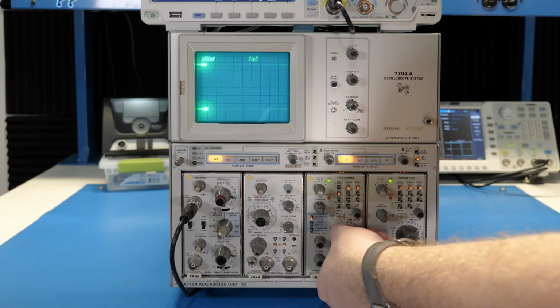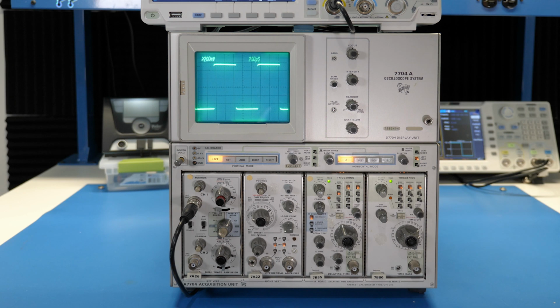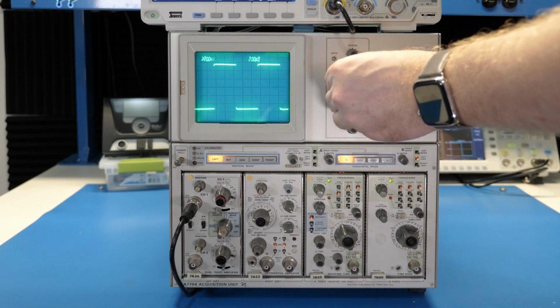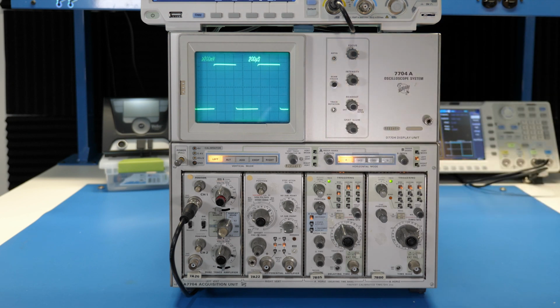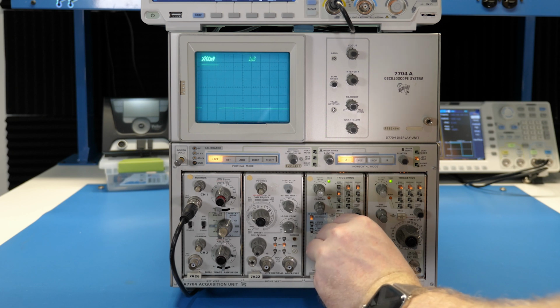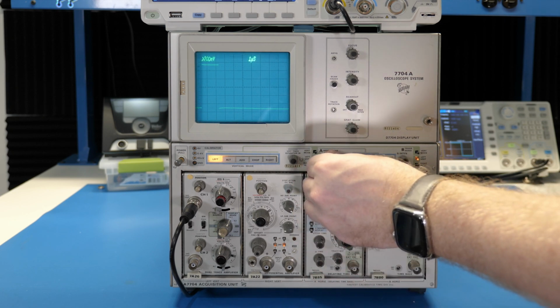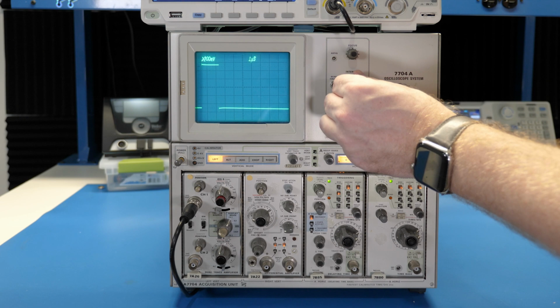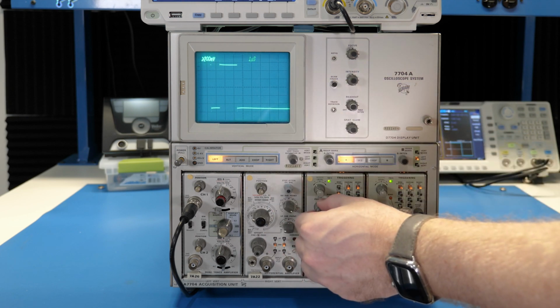So let's start by using the A module and setting it to 20 microseconds per division or 200 microseconds of time on screen. Now we can see the same square waveform that we've seen before. To zoom in, we have to slow down the time base to 1 microsecond per division, just like we did on the digital scope. Well, except here now we have to also mess with the position and intensity knobs to be able to see the waveform.